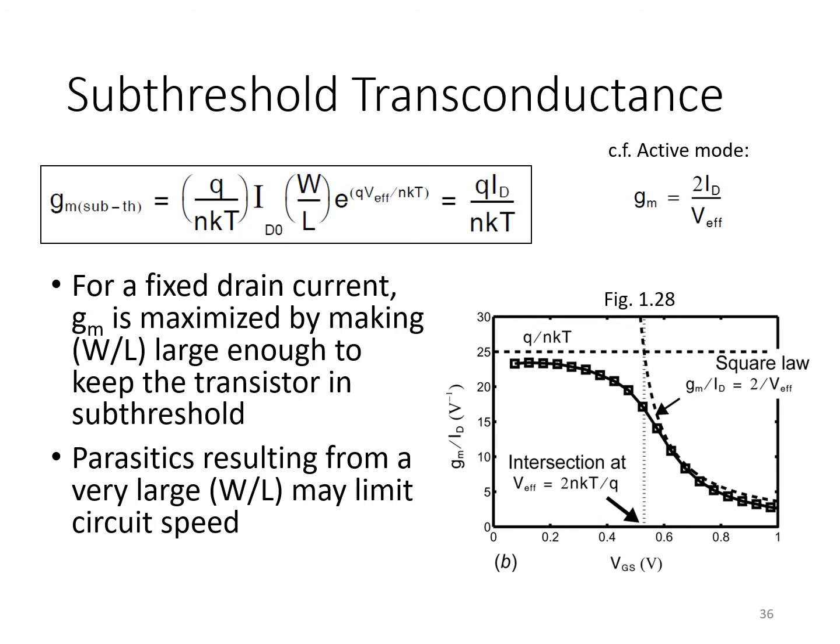Well, modern MOSFET models are so complicated. In order to properly capture second, third, fourth order effects, all temperature coefficients and so on, MOSFET models in modern technologies contain literally hundreds of parameters. So it can be quite difficult to infer the value of any given square law model parameter just by looking at that model file.